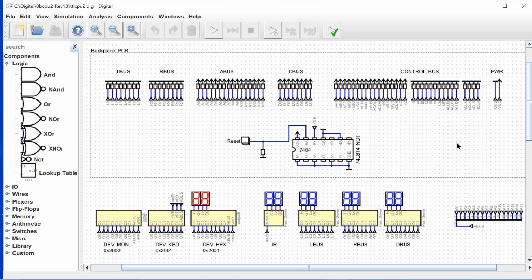One direction would be that we put all of the testing and the display elements that we would need to prove out the circuit board designs. We would put all those elements and build them into the backplane, like all of our data switches, visual indicators for the status of the buses and the control signals that we'll need to be able to do that to validate that the boards are operating correctly.